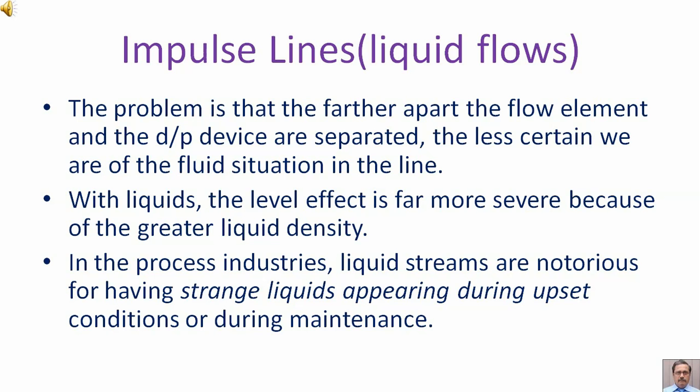With liquids, the level effect is far more severe because of the greater liquid density. In the process industries, liquid streams are notorious for having strange liquids appearing during upset conditions or during maintenance.